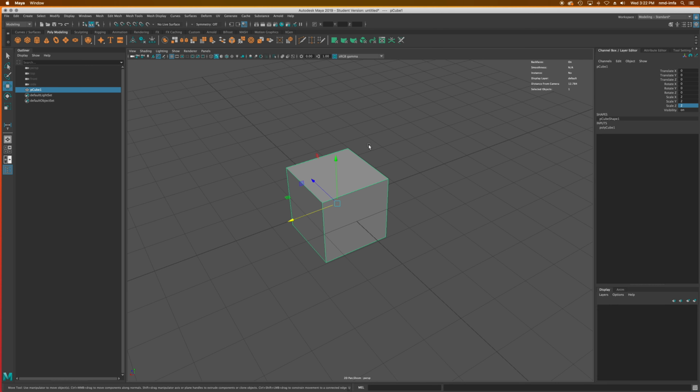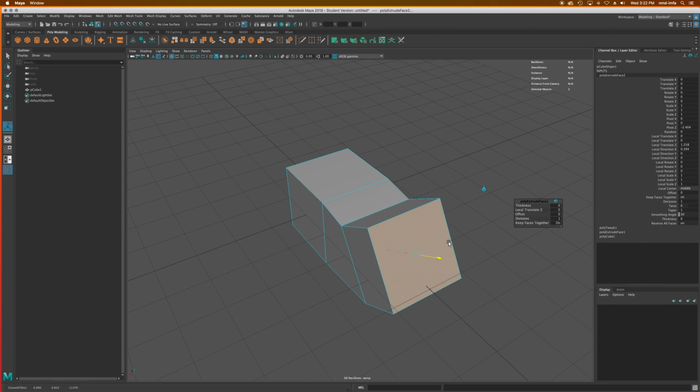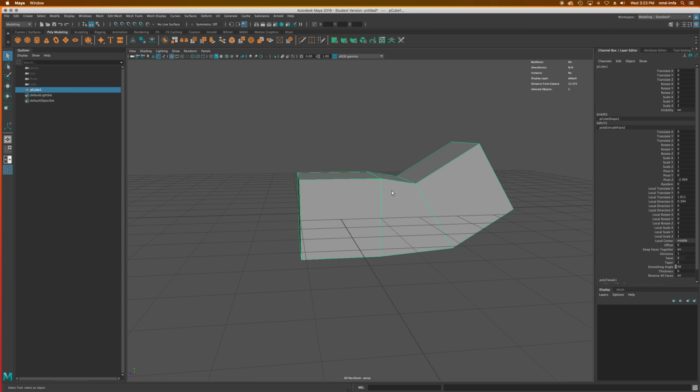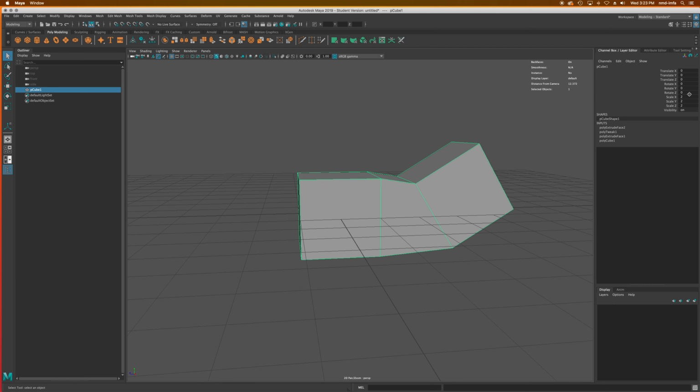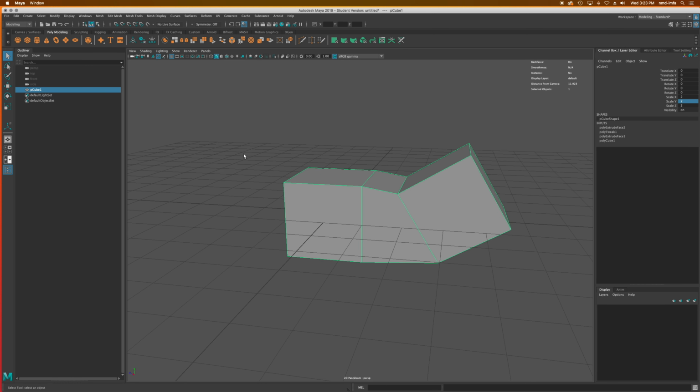However, things do get more complex as you begin to modify your objects. So say if I go to face mode here and I start extruding things and rotating them and playing with their dimensional qualities and whatnot, and then I come back and I go to object mode and I click on this, you'll notice it still says 2 by 2 by 2 because that was the original unit in there, but this object no longer is really 2 by 2 by 2, it's this other thing, right?